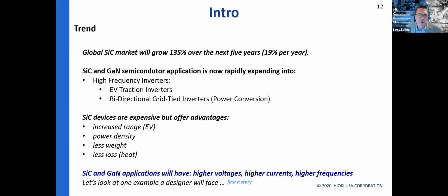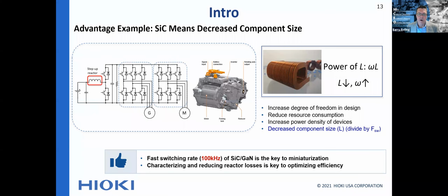and they were designing and testing a traction inverter, and they had 120% efficiency. And they were running a power analyzer that sampled at around 2 mega samples per second. And the story wasn't that simple. There were a couple of phenomena going on there, and our troubleshooting process didn't end in one day. We were there 3 hours, and I took that problem home with me, and we studied it. And I'll tell you how I solved that problem with a colleague of mine in a few more slides.